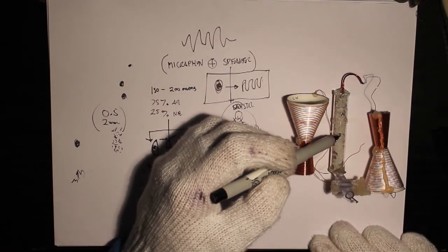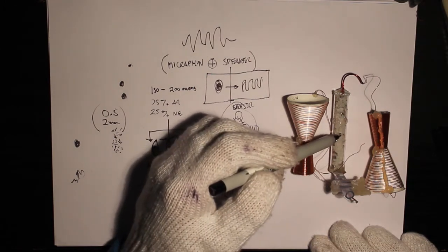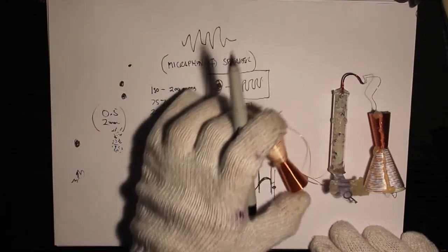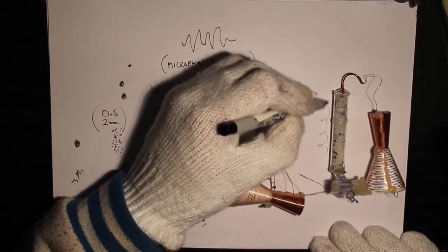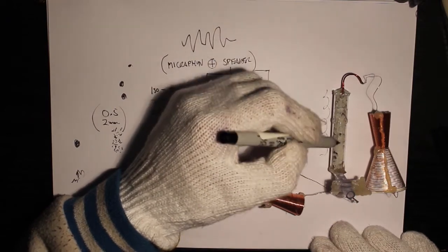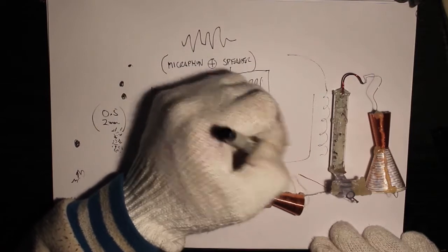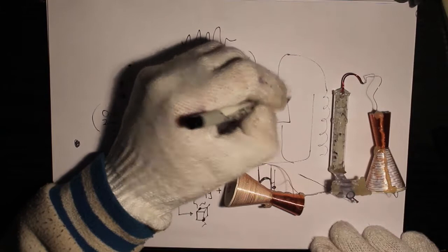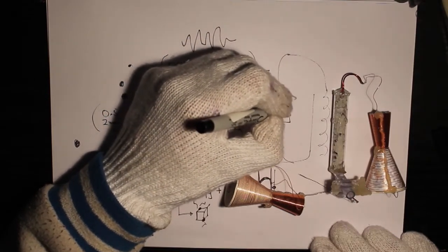I've tested it as a microphone by putting a speaker onto it and getting it to transduce. The way I pick up the signal is I have just one coil wrapped around the tube and a wire next to it for the energy coming off of it, and I run it into a phono input or a high resistance input into an amplifier and a speaker.